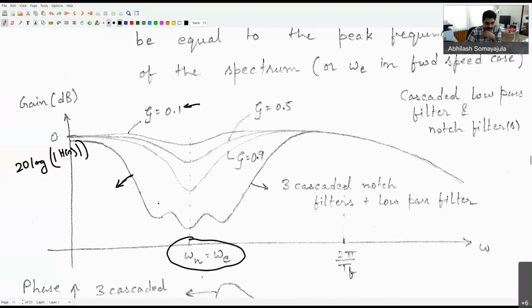You see that the first frequency is here, the second one here, the third one here. I'm trying to extend the range of the notch filtering effect by putting multiple filters with different frequencies together, so that over a broad range of frequencies, the wave frequency effects can be filtered out.